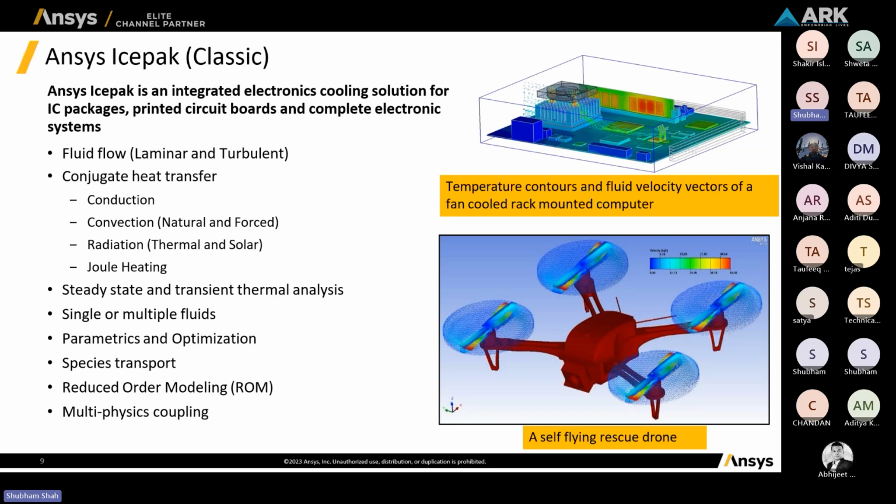The second way is where parametrics comes into the picture. You can perform the geometric parameterization, define RPM as a parameter, and give your values. You don't have to perform the simulation every time. Once you give the different parametric values, the system will itself perform the simulations. So this is the other option, and this is how you can proceed.